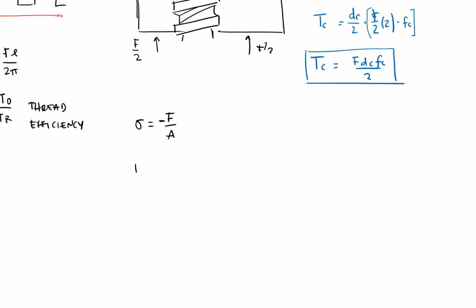We're going to use torques, obviously, and like I've mentioned 1,000 times in class, and we've done this before, for a cylindrical torque, this ends up being 16T over pi d cubed. So I'm assuming all of you are familiar with that, and that this would be the diameter, dr, which is the minor diameter, which is where the stress would be concentrated. And there will also be bending.